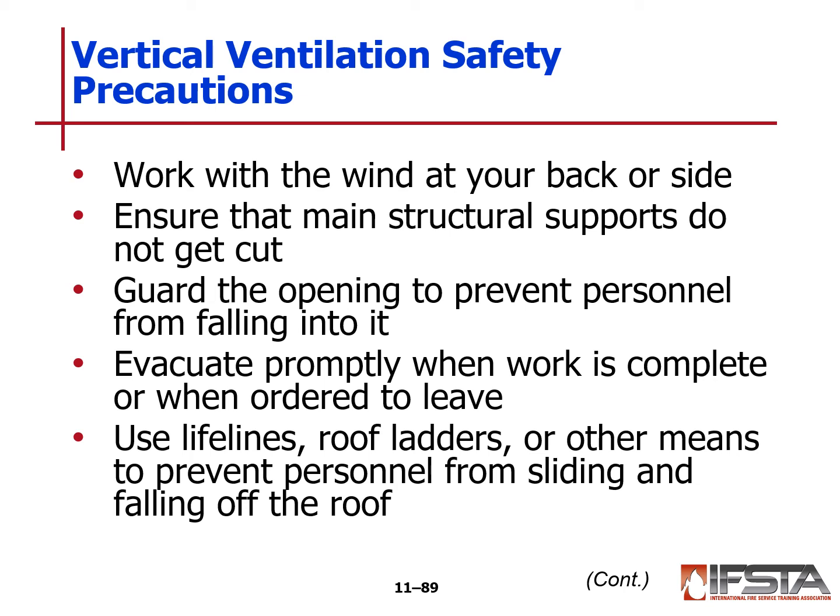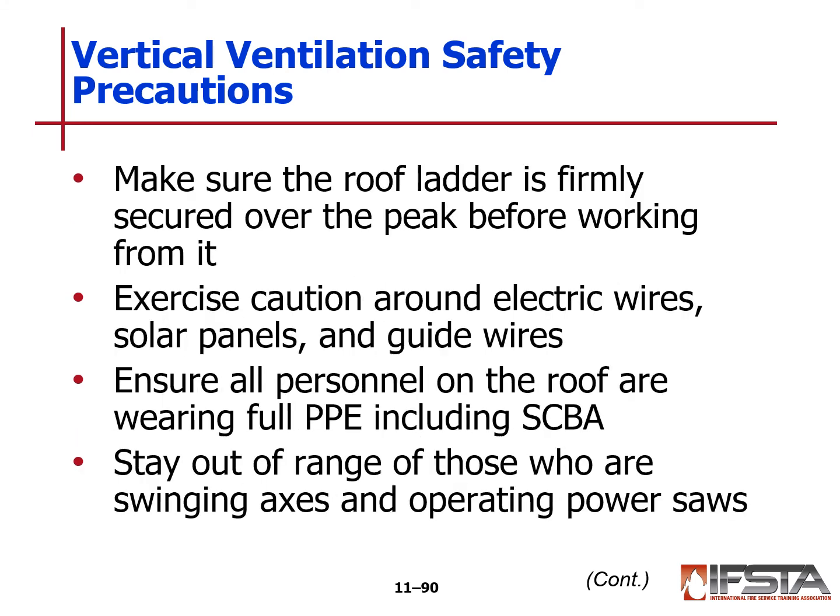Use lifelines, roof ladders, or other means to prevent personnel from sliding and falling off the roof. It is best to work off of roof ladders. That's what they're designed for. Make sure the roof ladder is firmly secured over the peak before we begin to work from it. Make sure that the hooks are engaged.